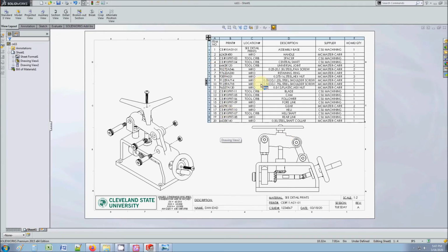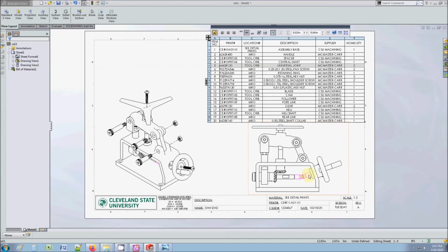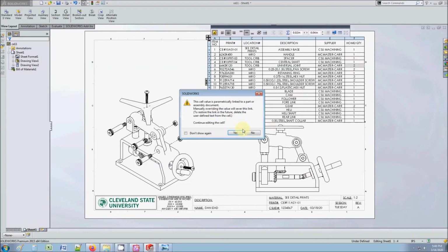Another thing I like to point out about this bill of material is that sometimes these numbers are not correct. You have to double check. Like for example, if you look at the universal joint, when you buy these, it comes as one piece. But here it's saying there's two. And you don't want to buy two if you only need one. You don't want to collect garbage in your desk. So sometimes you have to bypass this, okay? The only reason I have two is because I needed to create the animation that I wanted to create.